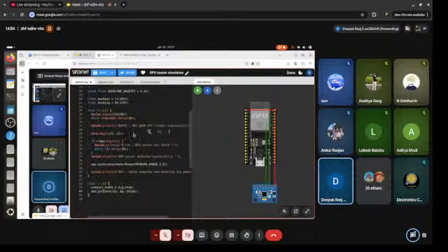Okay, so now we are using this getEvent to get all these values, that is acceleration, gyroscope and temperature values from the sensor. Next we have to calculate the total acceleration that the tracker experiences. For that we are going to be using the Pythagoras theorem.